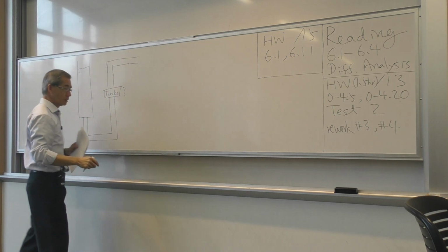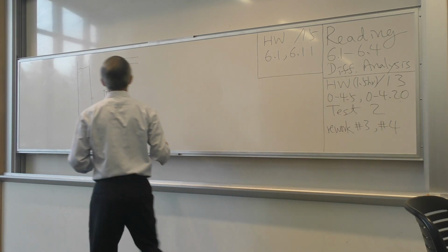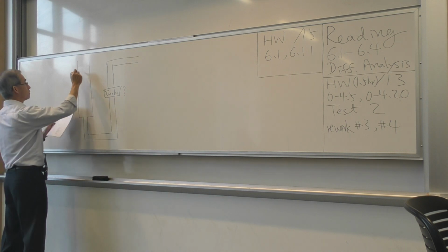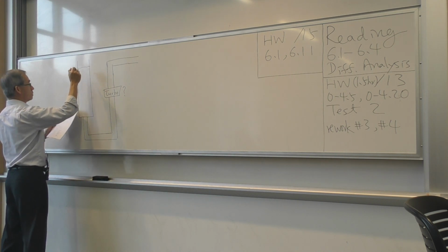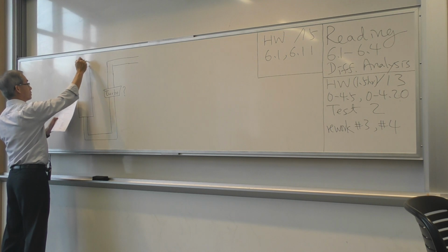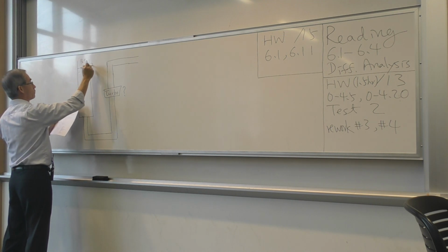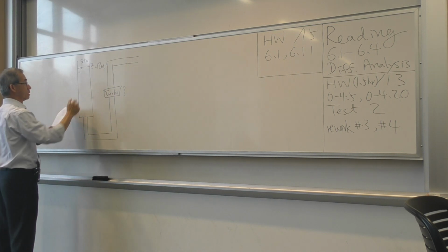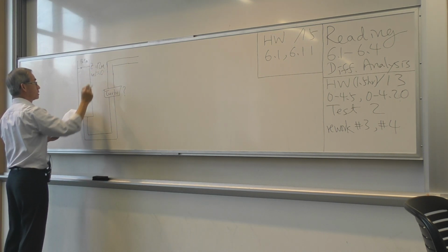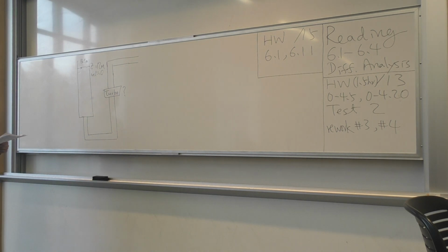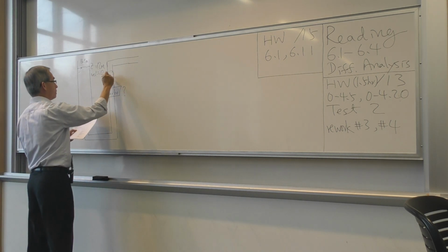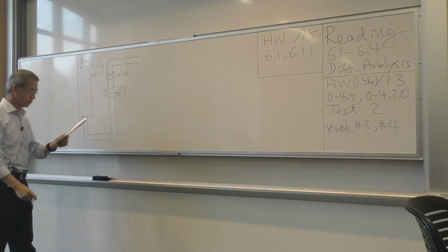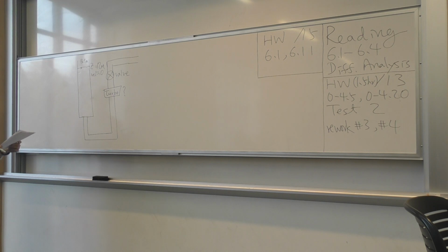So this height here and all this detail need to be drawn accurately. You have a reservoir where you are told the pressure is atmospheric at the elevation of 12 meters. You are even told the reservoir velocity, because of the large area, is relatively small. You have in the plumbing a valve and a turbomachine, the pump or turbine.